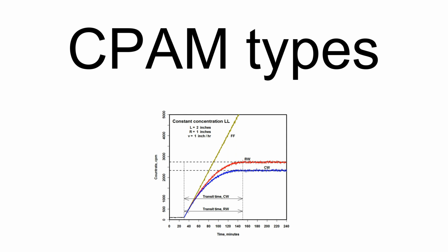Moving filter monitors are often used in applications where loading of the filter medium with dust is an issue. This dust loading reduces the airflow over time. The moving filter collection medium, tape, is assumed to move across the deposition area at a constant, known rate. This rate is often established in such a way that a roll of the filter tape will last about 1 month. A typical filter movement rate is about 1 inch per hour. The rectangular window moving filter monitor will be denoted as RW, the circular window moving filter as CW, and the fixed filter as FF.